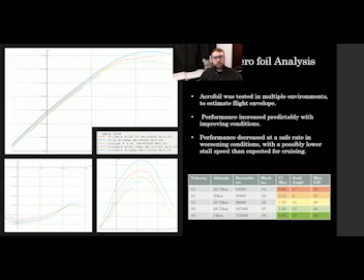Different environmental conditions were tested on the NACA 6308 by using the correlating Mach and Reynolds numbers associated with each condition. At higher velocities and lower altitudes there were clear improvements, with 12 to 15% better lift-to-drag ratio, 7 to 15% higher CL max, and 1.5 to 3.5% improvements in pitching moments.